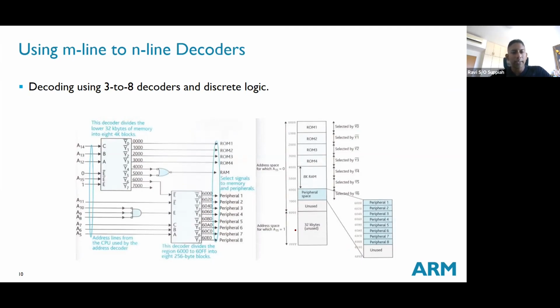Now, if you look at this address decoding circuitry, basically you have two decoders with some logic gates as well. Let's look at this first decoder. It is again a 3 to 8 decoder. It has 3 enable pins, which means all these 3 pins must be in the active state, then only this decoder is considered functional.